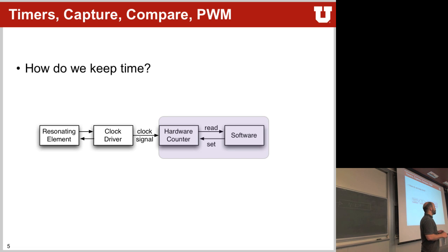What do you need? Just a connection from the last bit of the first to the first bit of the second. Basically an overflow signal, right? So there's a signal that pretty much every timer gives you when it overflows, when it goes from its highest number, so 2 to the power of n minus 1, back to 0. That's what's called an overflow. And in the SmartFusion they take that overflow signal and hook it up as the clock input of your next counter. So the next counter just counts how often this counter overflowed and technically thus doubles your bit length.